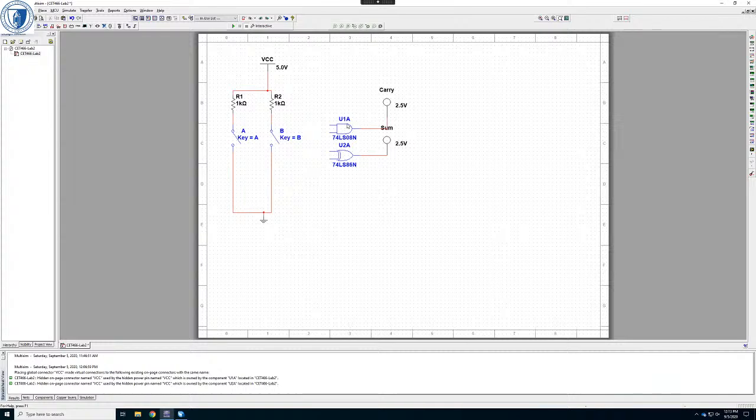They're very high impedance, so that means very little current will flow through them, even when there's a voltage. If there's very little current flowing through here, then the difference between the voltage on this side, which is VCC or 5 volts, and the voltage on this side is negligible, right? So the voltage here is 5 volts with this key open. The voltage here is 5 volts with this key open.